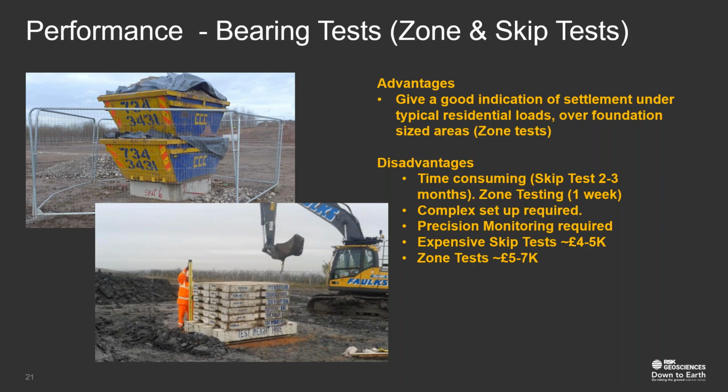And these really are large scale tests, which usually involve a large plate or concrete foundation, which is specifically cast into the ground, loading it up with a heavy Kentledge that you can see there.